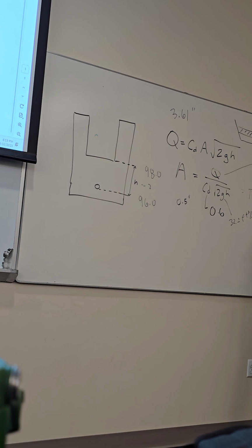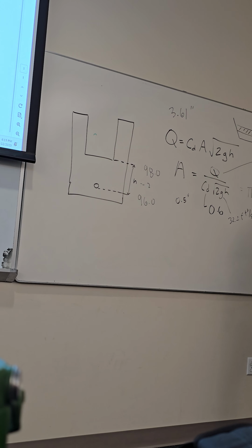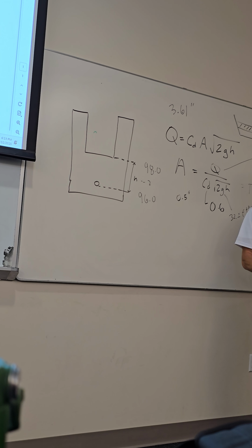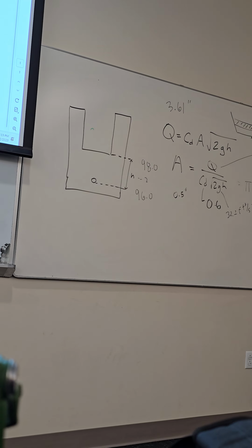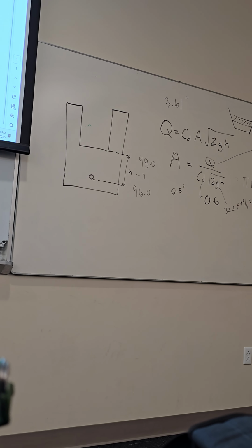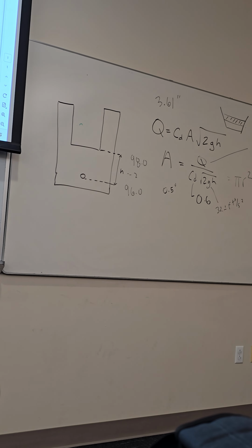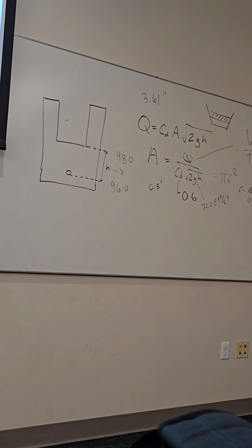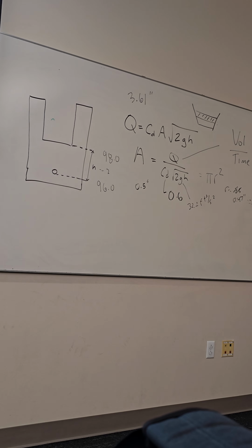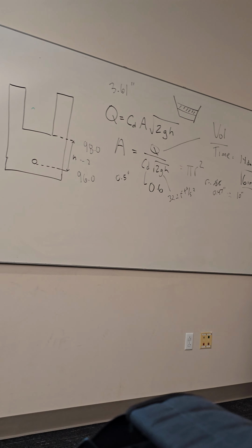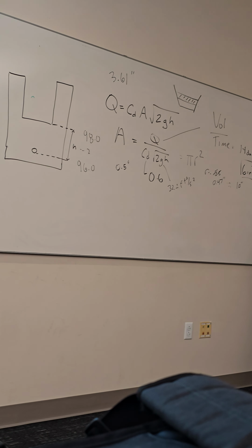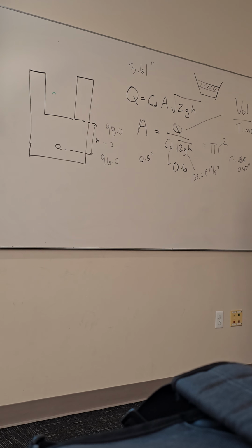Yeah, so if the orifice is less than 6 square inches cross-sectional area, then use 6. Yeah, you wanna use that. If it's over 6, then use whatever's over 6. Right. But again, that's an area, not a diameter. So I'll allow you to calculate what that diameter would be. Okay? Anybody else? Okay.